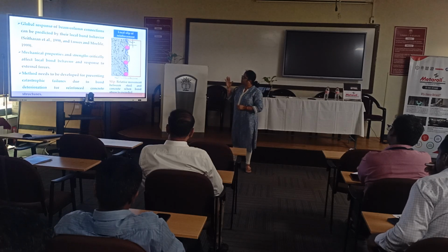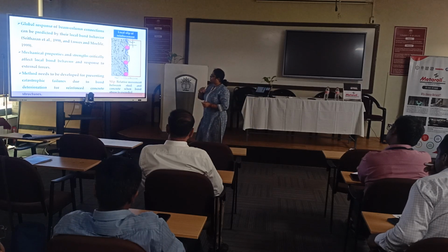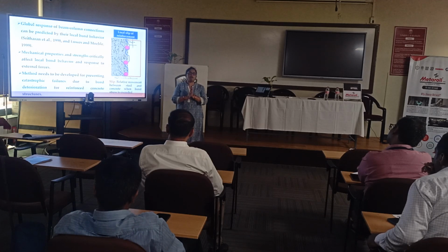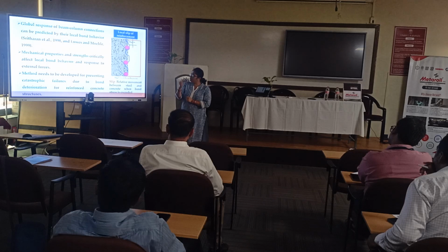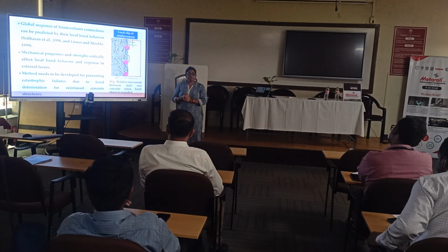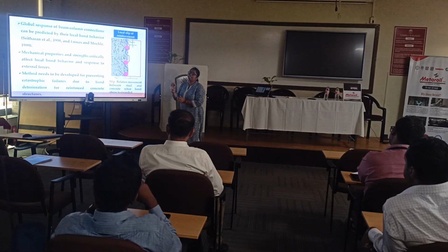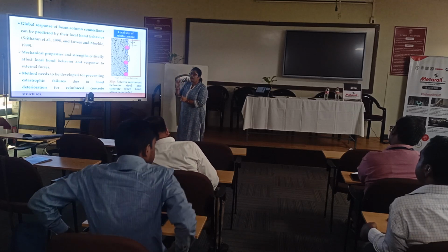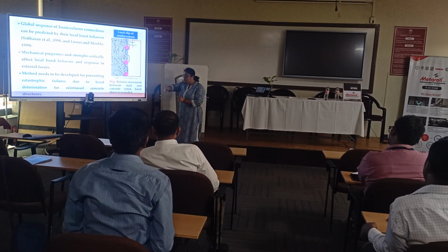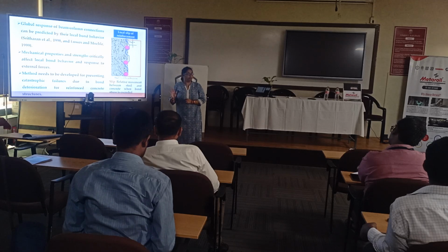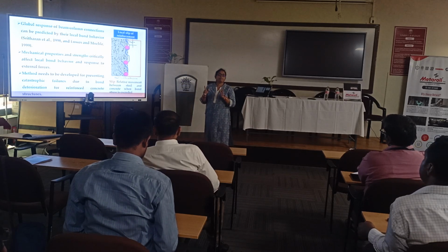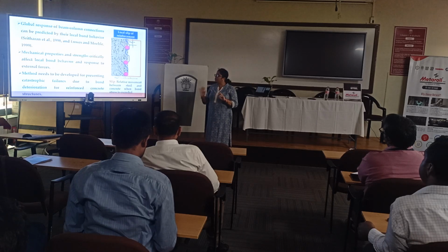So, first thing, what is the challenge? I will show you the challenge. But another important thing to understand is the slip. There is a relative displacement between the surrounding concrete and the steel while it is being pulled, which is called slip. And exactly what the slip displacement is in mm, and at what load the slip occurs, is very important to know, because that gives you the interfacial strength measurement, which has never been known in this condition.